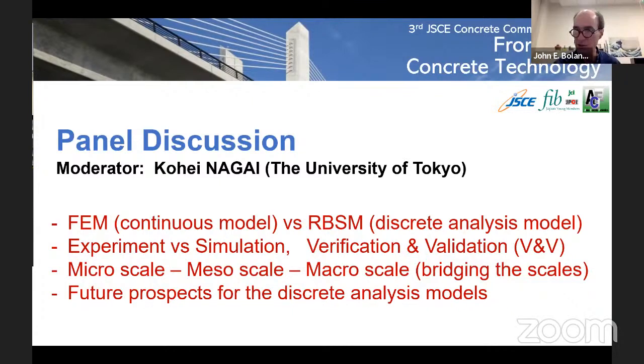When you have steel fibers, it's easy to use some sort of X-ray image or computed tomography. Steel fibers show up very nicely in X-ray images. We've done some comparisons when a slab was poured, and the pouring process induced bias on the fiber directions.